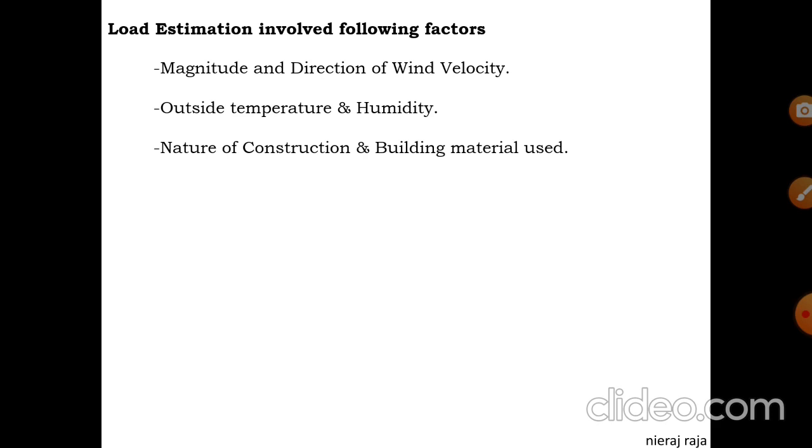That's why it is observed that the outside temperature is highest in the time zone of 12 to 1 p.m. But when the temperature is slightly reduced, that particular wall or ceiling or roof is going to release that heat at around 2 to 3 or 3 to 4 o'clock. So that is about the flywheel effect of your building material. That is an important thing: which material you are using and what type of construction you have.